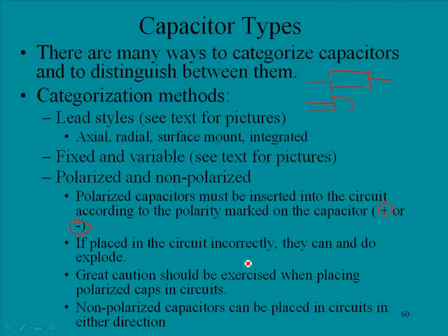Everybody thinks, oh my, capacitor in backwards. So oftentimes people learn this, but there is a hazard involved, so ensure that when you put them in the circuit, you're putting them in correctly. Non-polarized capacitors can be placed in a circuit in either direction. So non-polarized don't care, but of the polarized variety, you must use caution.